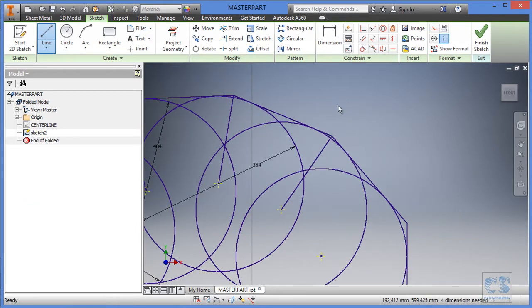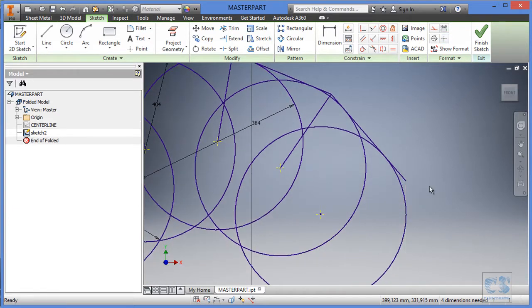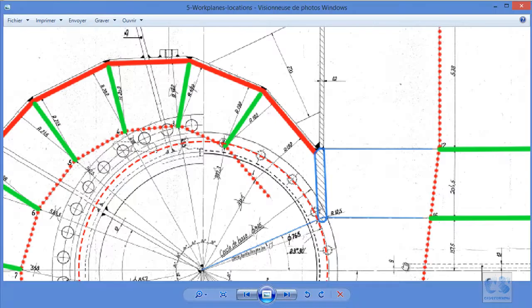Now escape to finish the line tool. We will delete this last line because we do not actually need it. This last one will represent the sheet metal component which meet the deflector. So to define it further, we need to build the deflector geometry first.